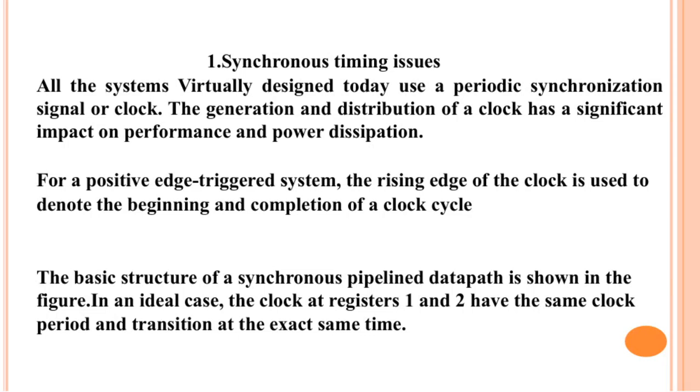Today, most systems are designed to work with a periodic synchronization signal, commonly known as a clock. This clock plays a crucial role because how it's generated and distributed can greatly affect both the system's performance and power consumption. In positive edge-triggered systems, the rising edge of the clock essentially marks the start and end of each clock cycle. If we look at a synchronous pipeline data path, the ideal scenario is that the clock's driving registers 1 and 2 have identical periods and switch states simultaneously, ensuring smooth and reliable data transfer between stages. This precise timing coordination helps prevent errors and optimizes system efficiency.